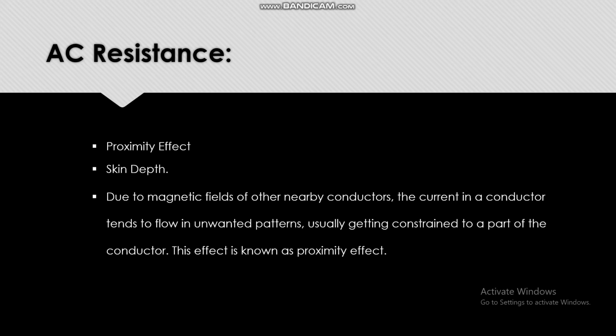Foil windings have superior skin penetration depth. The AC current doesn't simply stream on the external surface of the wire. However, it increments if foil thickness increments for high power transformers. Dowell's work is generally used to compute the AC resistance factor for a given conductor. In the next slide, we'll be discussing how to diminish proximity effect; the factor should be near to 1.